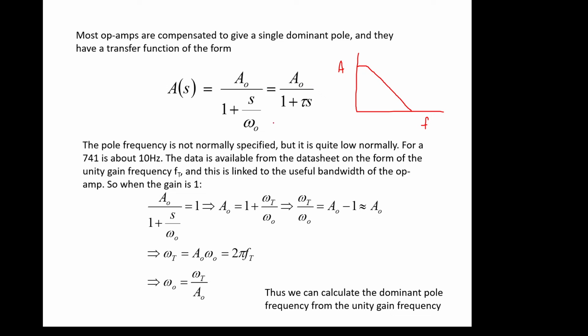Okay, so this is defining what's going on with that single pole transfer function, and this is where the pole is, the point where it starts to change direction. And we can define that in many different ways, but it's just a time constant times s, where s is the Laplace operator, and we would normally replace it with j omega for steady state response.